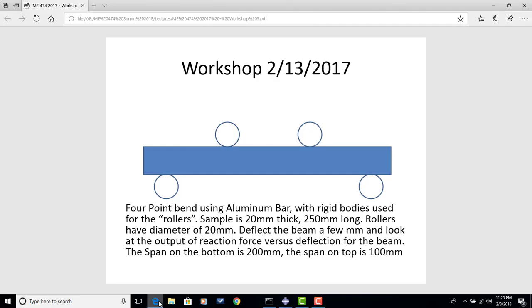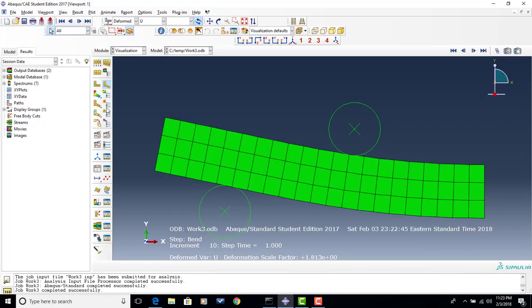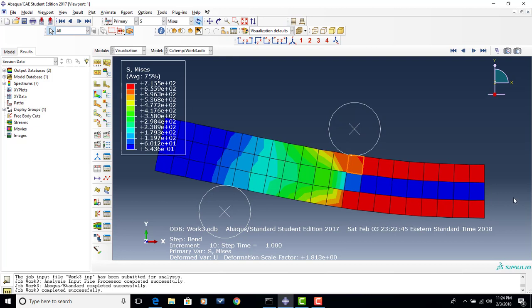So now at this point, I think it was just asking us to poke around and see what sorts of values we have, so we can look at contour plots. And again, maybe we could say that we probably could use some refinement in here, since we've got a very coarse contour of going from one max to the other max, and then back to the other max again, all within just 3 elements. So, in an ideal world, we would probably control that a little bit better. But again, for our purposes, we can at least get the idea of how to do it. And if we were using the industrial version of the software, you could apply as much mesh to that region as you would like.